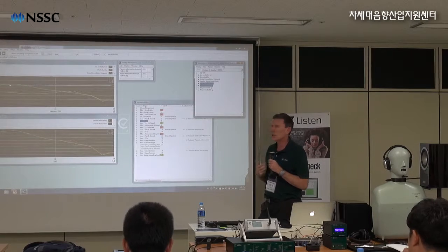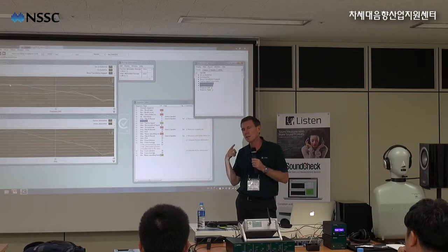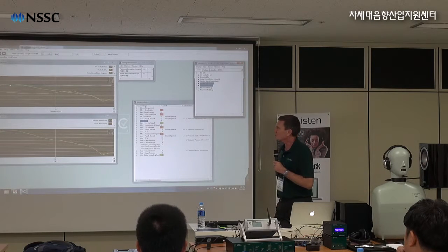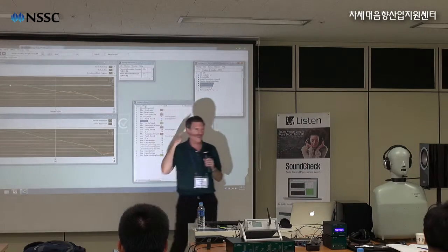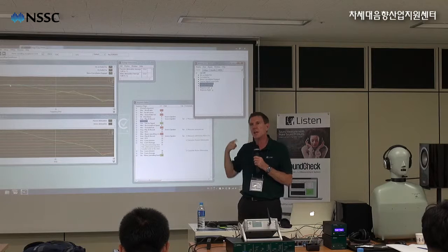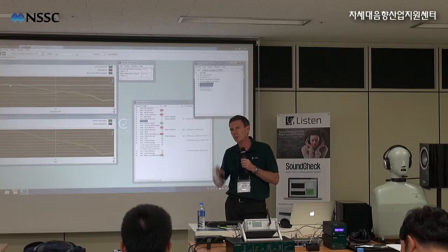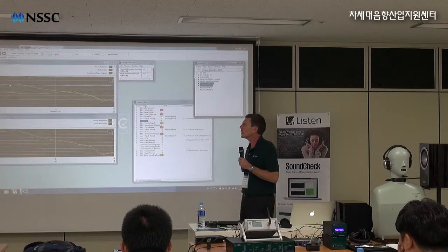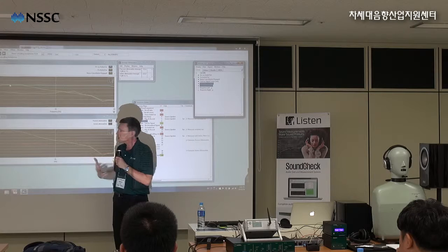But the noise cancellation circuit is a feedback loop, and that feedback loop has basically a high frequency limitation. It doesn't matter how well you design your noise canceling circuit, you're going to see some of this. And what's happening is, at the higher frequencies, instead of it being a feedback where it's canceling, it's actually feeding back on itself and causing a gain. So it's no longer 180 degrees out of phase, it's actually somewhat in phase. So we typically see this little bump, and it's just a compromise.